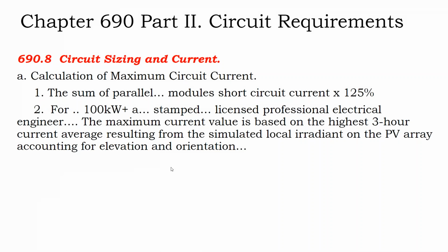And so far we're in the normal realm of electrical oversizing to calculate the current requirement for the conductor. We're just adding 25% onto it. Or it says you could get an engineer to figure out the actual amperage and stamp it.